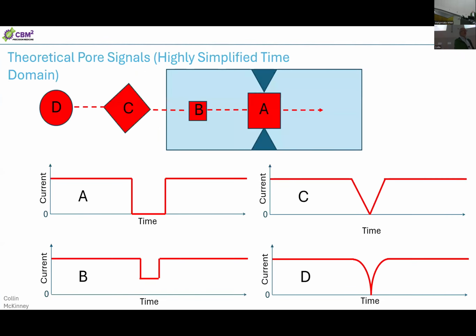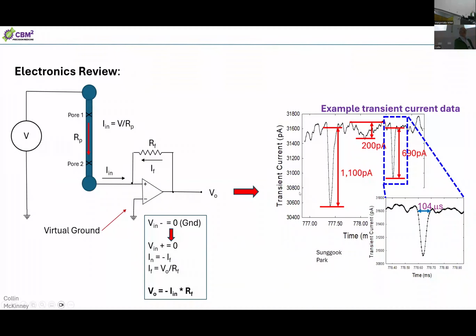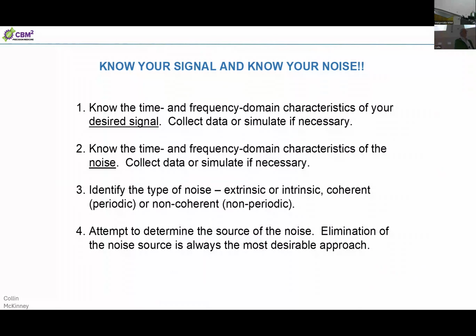So when we go back to this time domain noise here, what can you tell me about that noise? You look at it and you know, yeah, it's noise. It's not signal, so it must be noise. But I'm saying you need to go into that in more detail. What kind of noise is it? Is it extrinsic? Is it intrinsic? Extrinsic noises are those that come in from the environment, or there may be man-made noises. They may be environmental noises, whatever, that are externally impacting your experiment, or they could be intrinsic to your experiment.